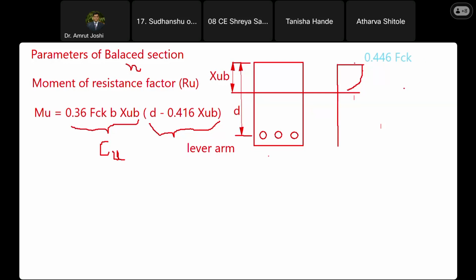And on tension side, the entire concrete on tension side needs to be neglected. Only the element that offers resistance in tension is the steel nearer to the bottom face, and at the level of steel, therefore I am going to show the resistance offered by the steel, and that is tensile resistance. So it is going away from the cross section.